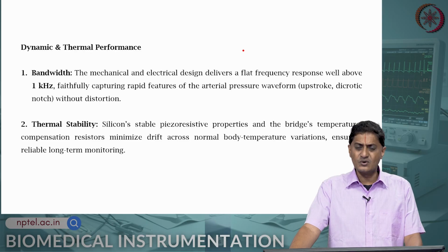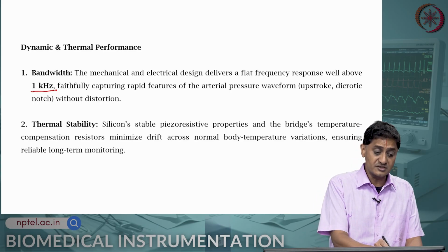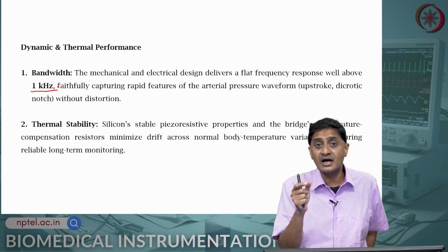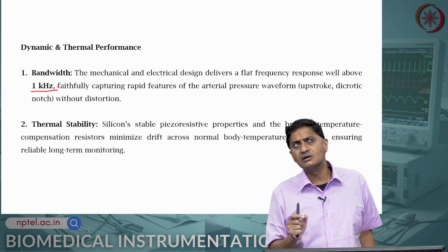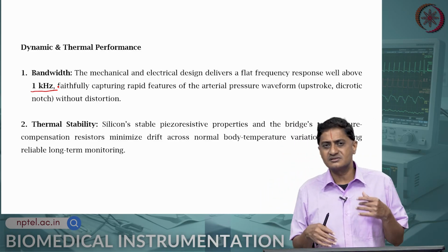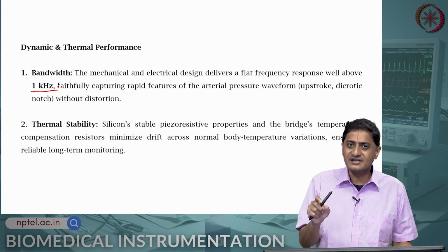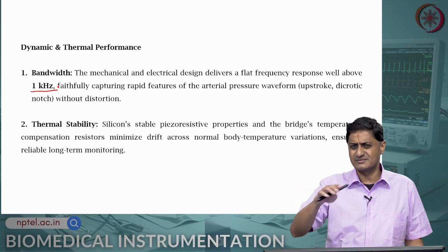The design is so good, so highly specific, that it provides a frequency response of well above 1 kilohertz, which means that any pressure change that happens at a time resolution of 1 millisecond, I can capture. Can I do that? Well, it is 1 millisecond I can capture, but also account for the Nyquist criterion and other such things, please do check those.